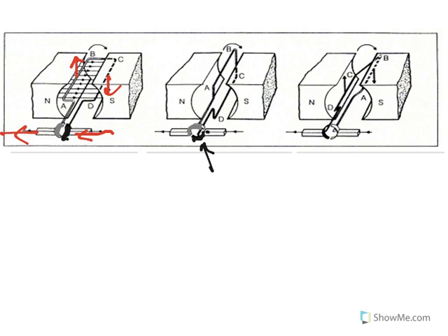When it rotates a bit more, because it'll have some momentum, the black one is now contacting where the current's going out. So down here the current was going into the black one, now over here the current's going out of the black one and into the grey one. Alright, so what that now does, it's now changed the direction.